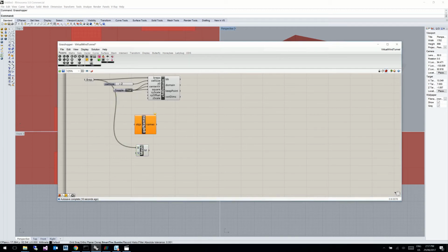We also want to just get the names from the BREP objects. Now by default it just gets the basic GUIDs, but you can actually set names back here if you wanted to assign a specific name to certain BREPs, but we'll get onto that in a later tutorial. You then want to actually set the names for those primitive mesh objects. Here's your objects, and there's the names that have been retrieved from the BREPs.